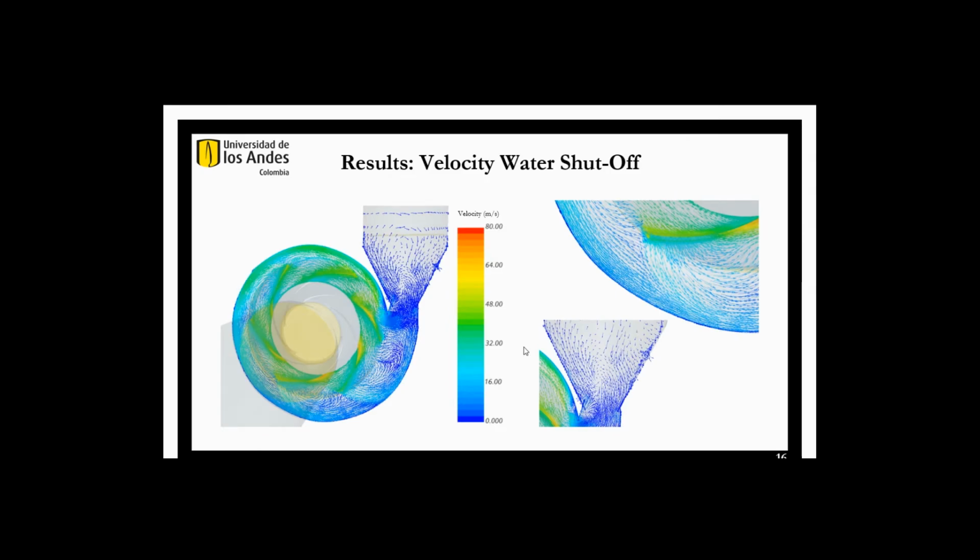In this scene, it's possible to observe that the fluid has a kind of recirculation in the area of the pump dome. This event can be attributed to the geometry in this area, since there is an abrupt change in geometry. However, the centrifugal force that the impeller imparts to the liquid when it enters the rotating zone must also be taken into account. It drives the liquid towards the wall of the volute, causing a recirculation in the middle of the discharge zone. By decreasing the rotation speed, you can avoid this phenomenon.